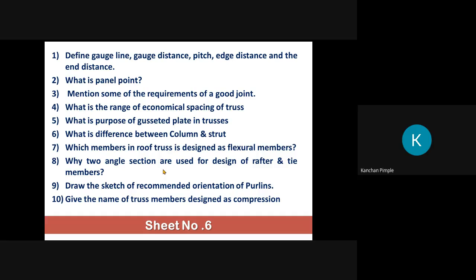Yes, madam. So just remember the purlin is a flexural member or bending member, and the gantry girder, a laterally unsupported beam, is again a flexural member. Just keep in mind both are flexural. Also in steel structures, the plate girder is a flexural member. Is it clear?